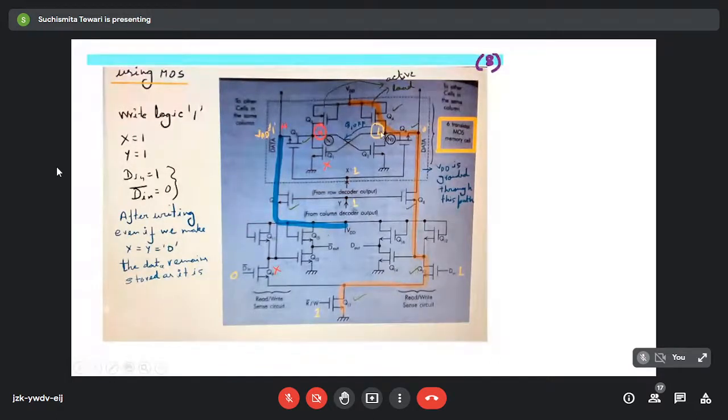Okay, now this logic level is falling here. It is low and it is applied to the gate terminal of this transistor. That means it is getting a 0 at the gate, so this transistor is now off. As soon as this transistor is off, this VDD is not getting any path straight to ground. So the potential at this node will be pulled up to high logic level. So this terminal, this Q1, is actually giving this high, or logic 1. So we tried to write, or to store, this one. Now it is being stored in this basic memory cell only at this node.